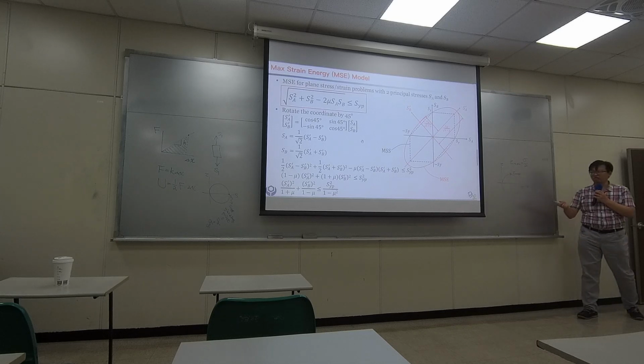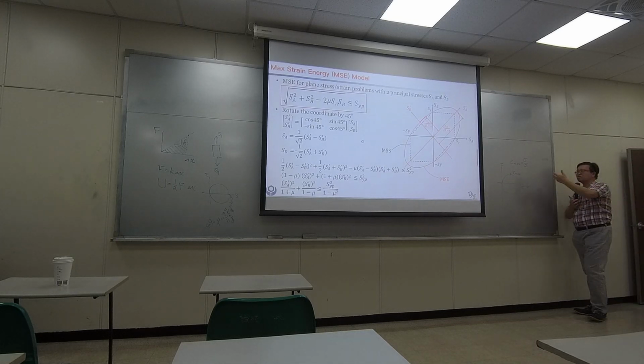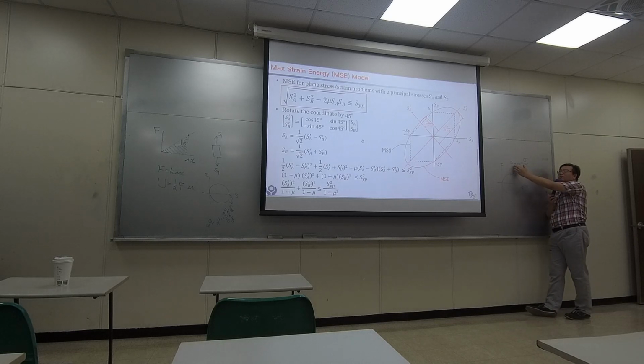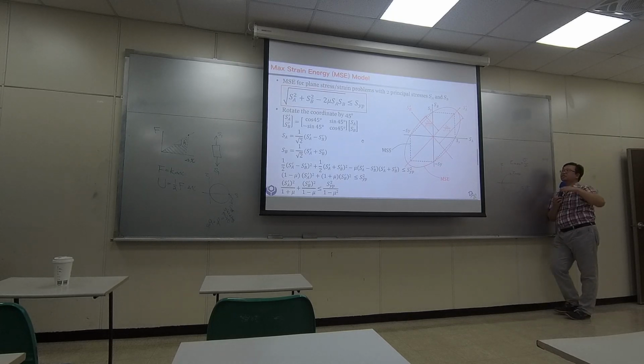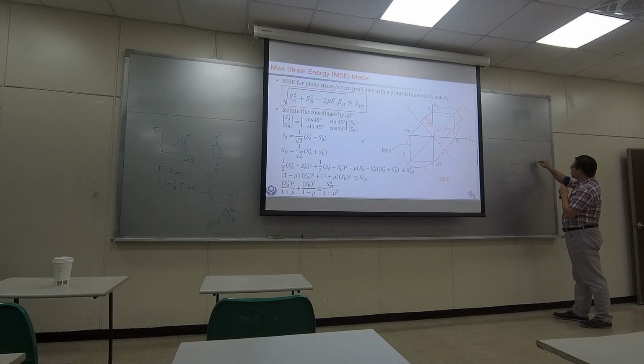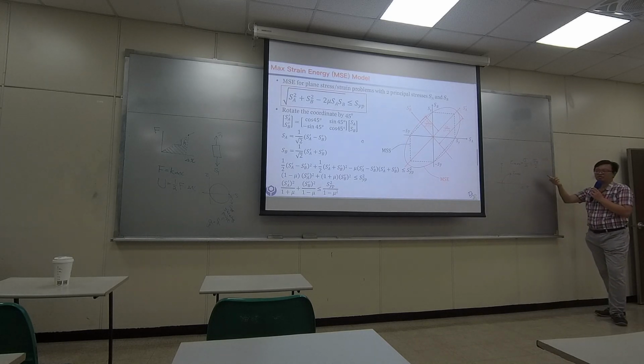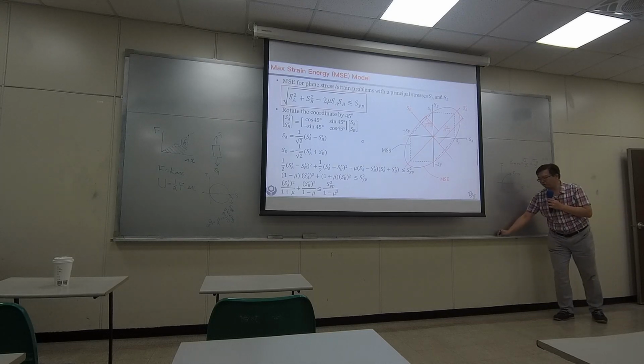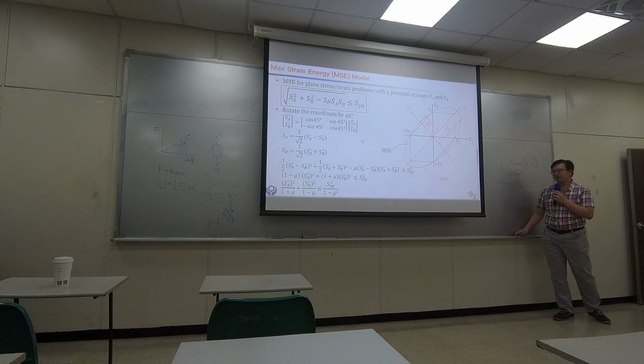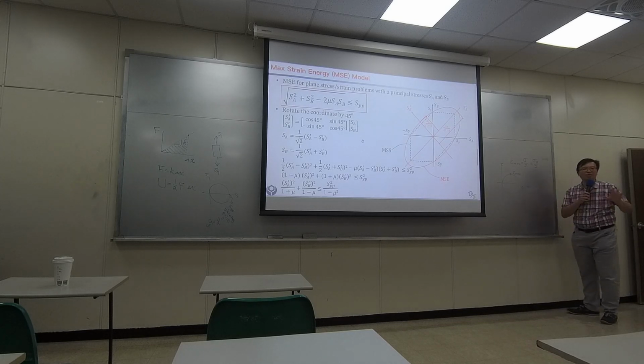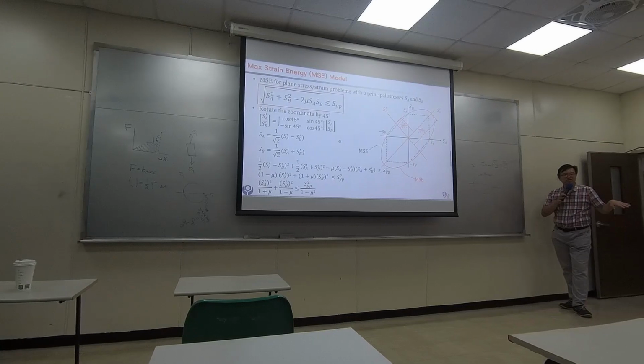If you have a Mohr's circle for the tensile test, you know from the maximum shear stress model, basically it's a number linearly proportional to the stress you apply. We just claim how much this value should be constrained by the upper limit. So usually we will say, okay, it's gonna be like this. That's how we have a design equation for the maximum shear stress model. When we deal with this equation, we never talk about what happened along different directions.